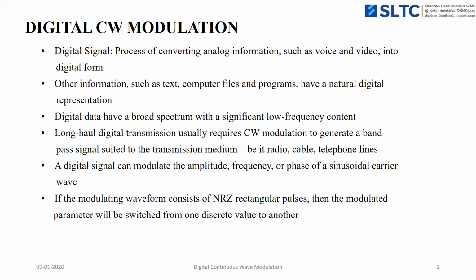By using a digital signal as the input signal, we can modulate either the amplitude, frequency, or phase of a sinusoidal carrier wave. If you consider the input signal as NRZ rectangular pulses, then the output modulated signal switches its amplitude from one discrete value to another discrete value. Here the input signal is the modulating signal and the output signal is the modulated signal.